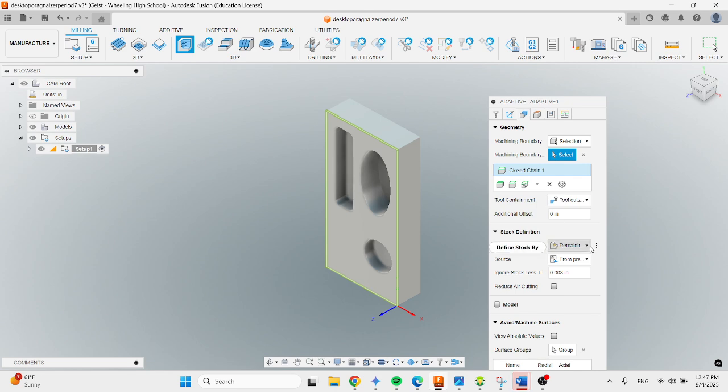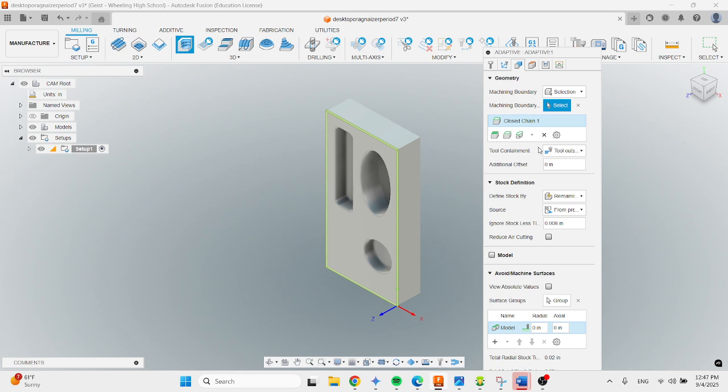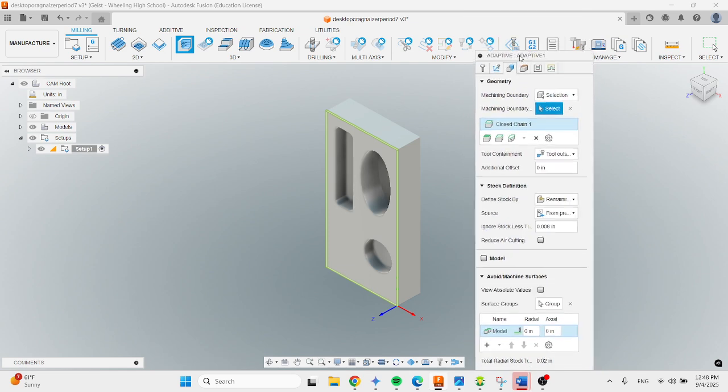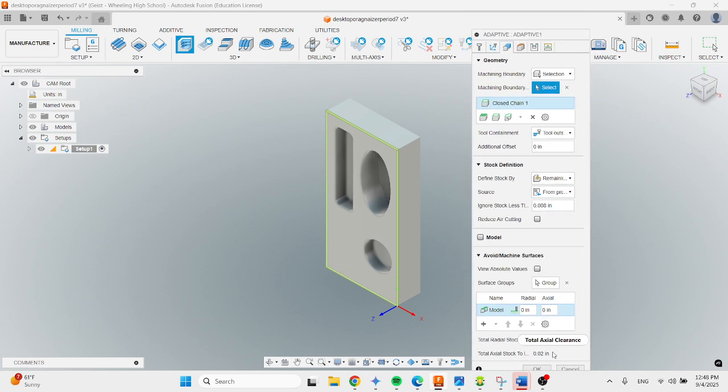So a lot of this data underneath here is telling it the details about how it should cut the grass, if you wanted to call this like a lawn. And we're going to, again, discuss more of the details within here and how it can affect the geometry. But the default for what we're doing should be okay for most of the parts that we're producing. So we're going to leave the geometry settings alone and really just pick that bounding box.